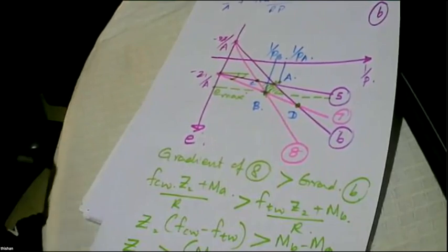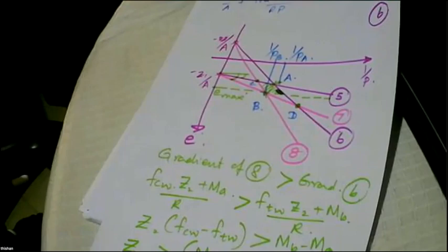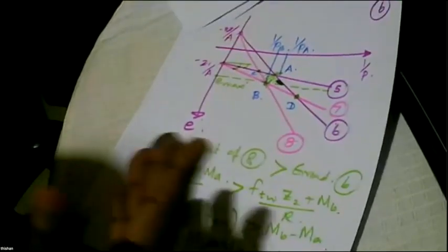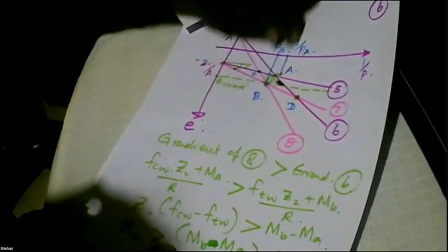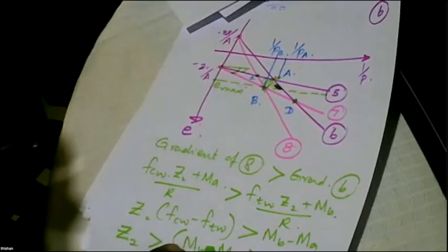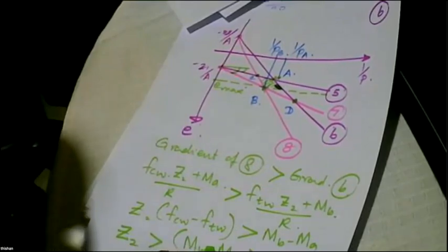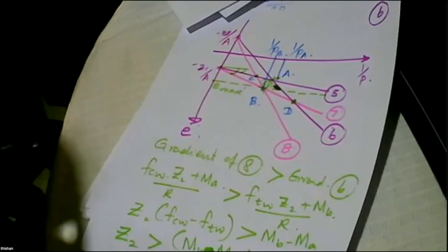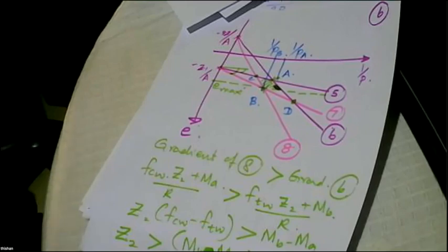So now you can see, if you are selecting a pre-stressing force, in which region we should select it? We should select it in this region. Why? Because the pre-stressing force is as minimum as possible. So you can see something very interesting. Along the beam, the Magnel diagram is going to move like that, because these PA and PB are independent of the bending moment, but dependent only on the section. So PA and PB will depend on the section sizes, not on the bending moment. And when you are designing, we always make sure we select a force that's as close as possible to the minimum. So those are the important things you can learn from what I have explained today.